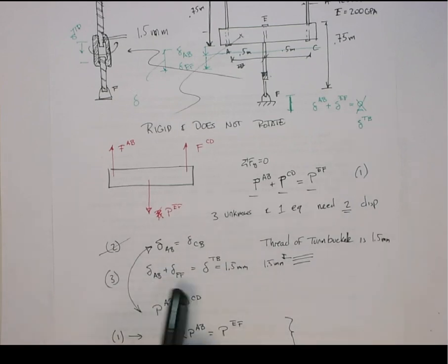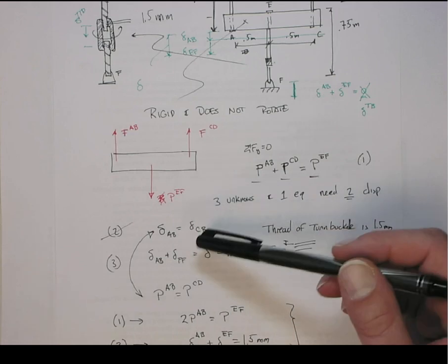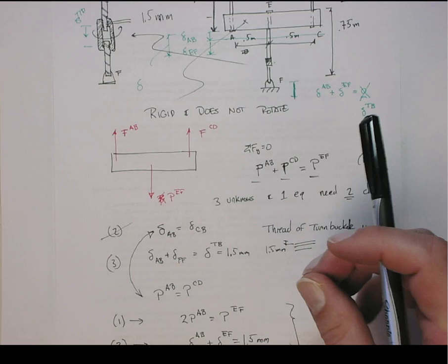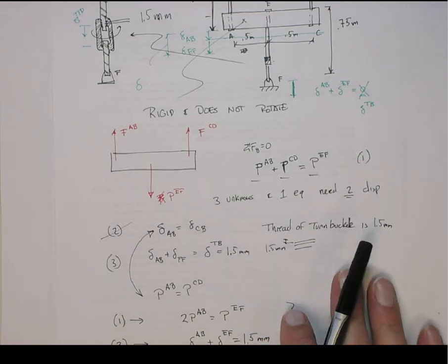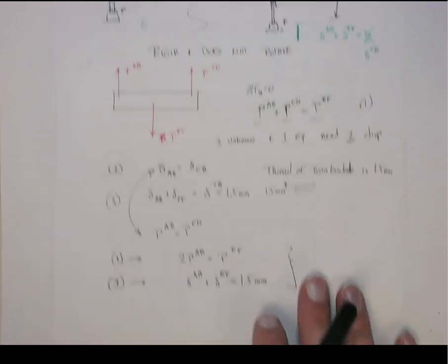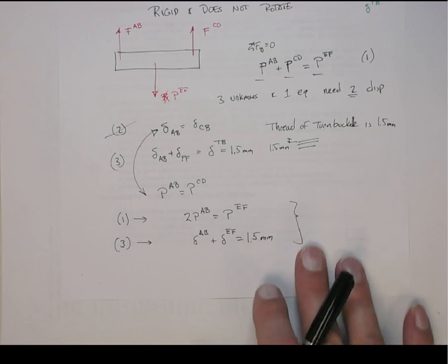But since you're solving for these coupled systems, you need to have the same sense on P as you do on the deltas. So in other words, if you just always assume that delta being positive means elongation, and that the internal reaction force is positive in tension, then you'll always be consistent. And I think that makes sense. If you start flipping them around, then you certainly can do it, but you just have to be very careful about the signs. And it's usually very difficult to do something like that, especially on an exam.